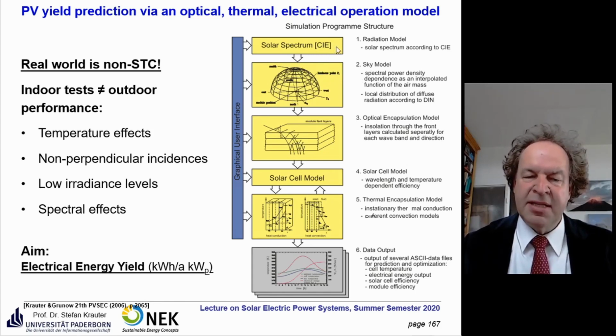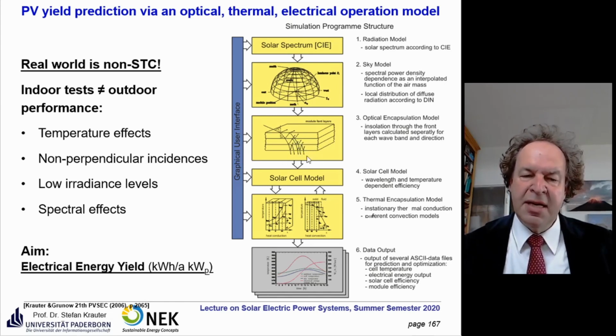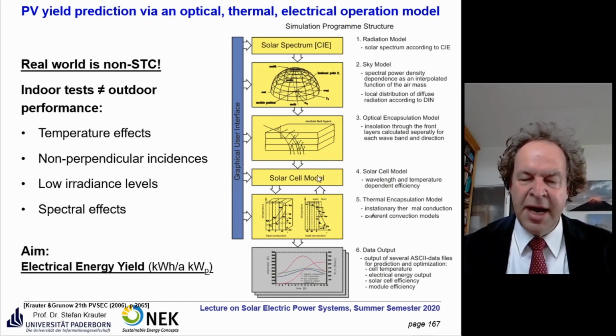So I made a quite extensive radiation model with the spectrum at the different parts of the day, the adequate incoming incidence angles on the module, then the reflection on the module, not only on the surface, but also in the different layers, considering also re-reflection within the layers, and interference. And at the very end, I calculated the cell-reaching energy flow and the part that could be converted, depending on the actual condition of the solar cell.